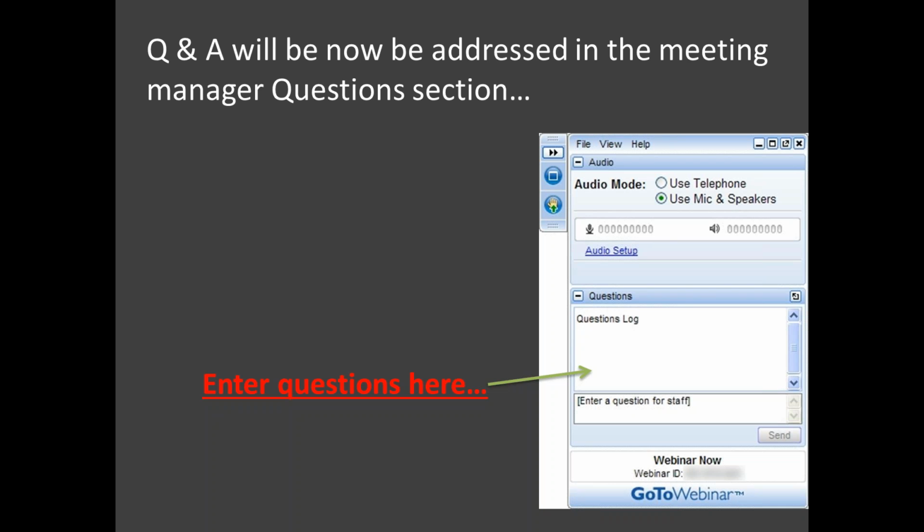What that does is it automatically scales everything accordingly based on that shrink rate. So they automatically get an as-cast design of their assembly. And very quickly, when they want the machined or the shrunken, they can have a drawing for the mold. And when they want a drawing or a model of the actual cast, they just take that shrink rate out and set it back to 1, take out the actual multiplying factor. We have a handful of customers doing that.